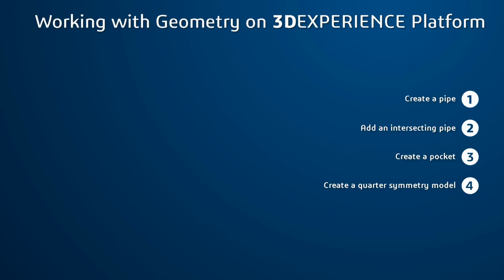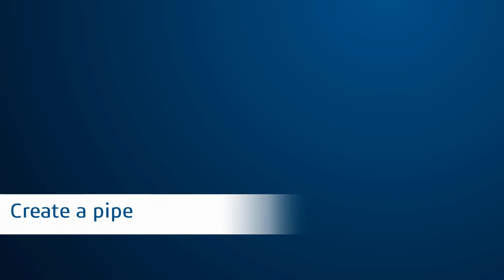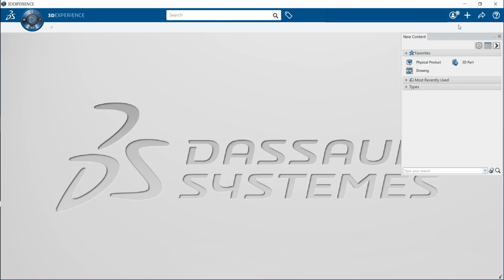In this video, I am going to show you how to create a three-dimensional geometry on 3DEXPERIENCE platform. Now, let us create a new 3D part. To do so, select a new content command from the Add menu.